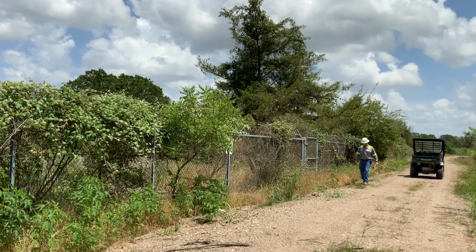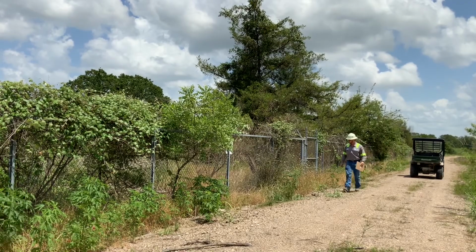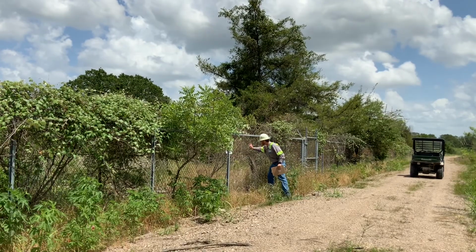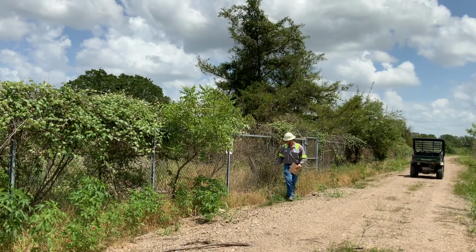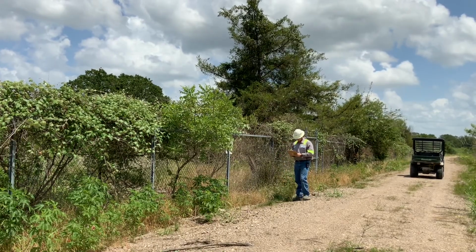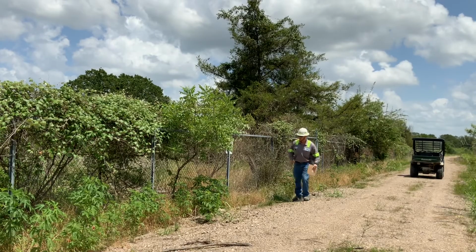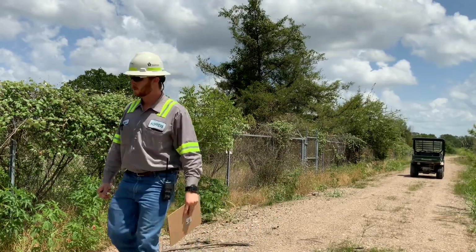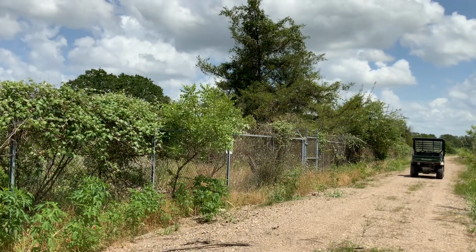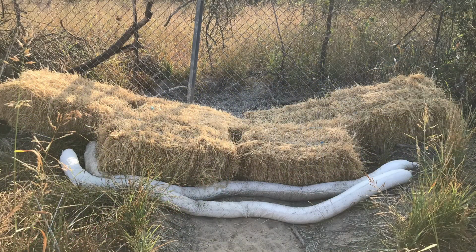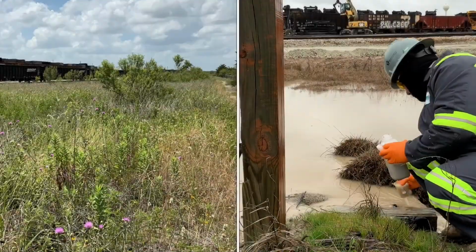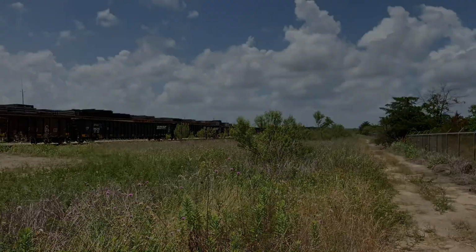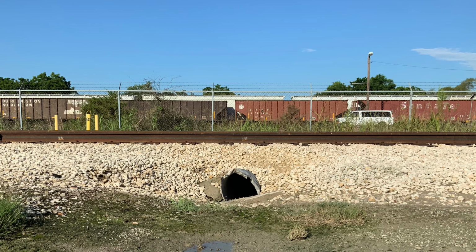Frequent stormwater inspections are the key to improving stormwater activity and preventing issues of noncompliance. The 3 stormwater inspections performed are periodic monthly inspections, quarterly visual monitoring inspections, and an annual stormwater site compliance inspection. Items evaluated during these inspections include structural and non-structural controls, any non-compliances, drippage from treated wood storage yard, open chemical containers, signs of erosion, exposed materials and supplies, and evidence of leaks and spills. During visual stormwater monitoring inspections, the color, clarity, and overall appearance of stormwater is evaluated.